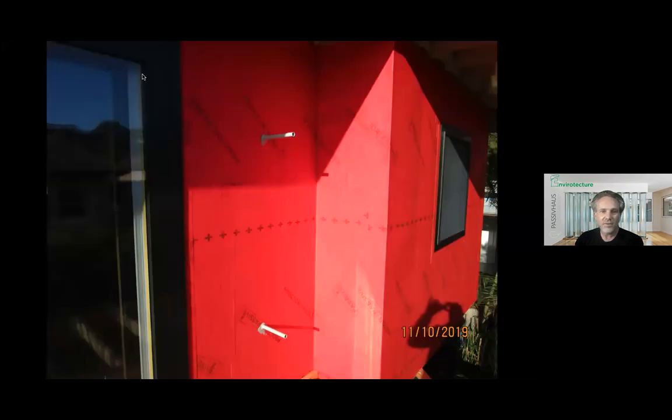I put these in just to show this is actually where a light fitting goes and a power point. But when you put a hole in an airtight building, you need to seal your hole in the airtight building, which is sort of obvious, but not unless you think about it. So every time anything goes through it, you firstly try to minimize it because it's more work.